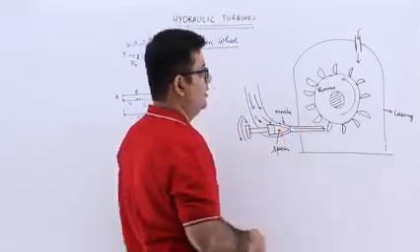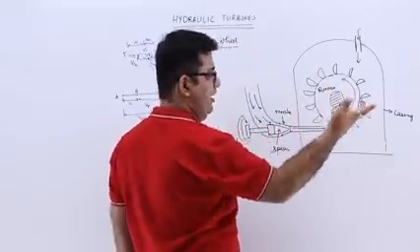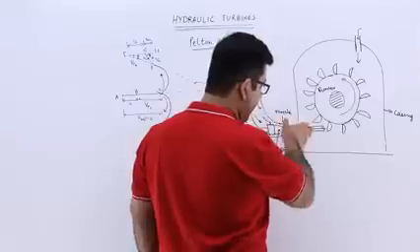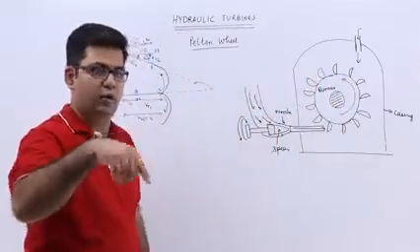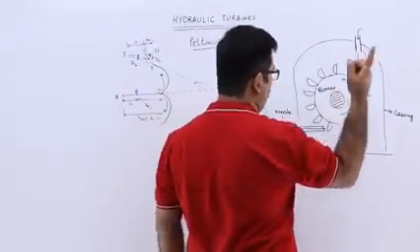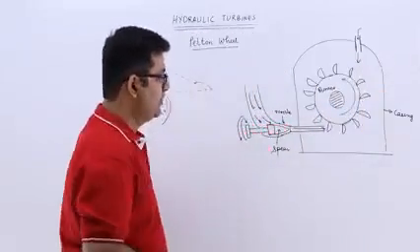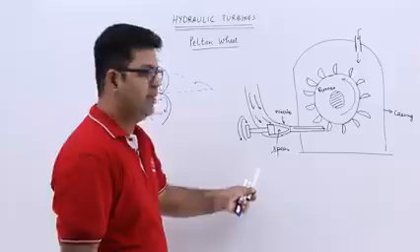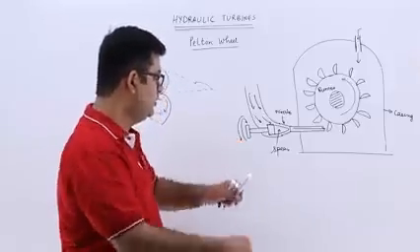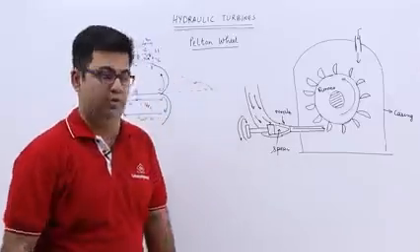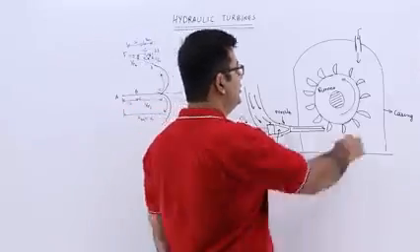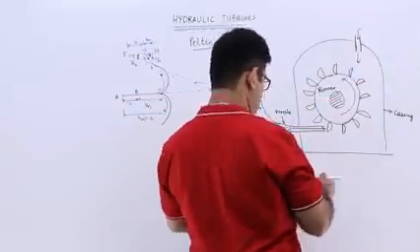strikes the buckets. So these are your buckets or vanes. So when it strikes, the entire wheel or the runner starts to rotate, and along this shaft you have some alternator attached. Okay, and then you have a spear. This spear you can turn like this, and you can control the flow rate through the nozzle. Okay, now this is another inlet of water.